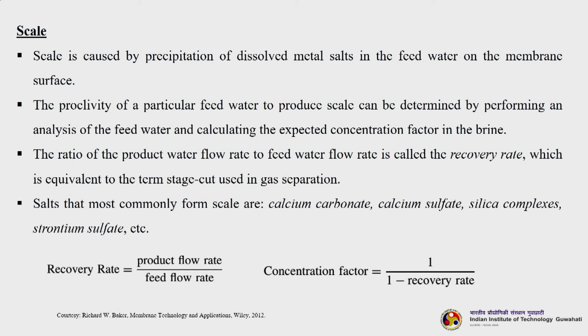So, you need to calculate the recovery rate as well as the concentration factor to understand how much scaling is possible using a particular seawater, or you can call it feed water. The ratio of product water flow rate to feed water flow rate is called the recovery rate, which is equivalent to the term stage cut used in gas separation membranes.